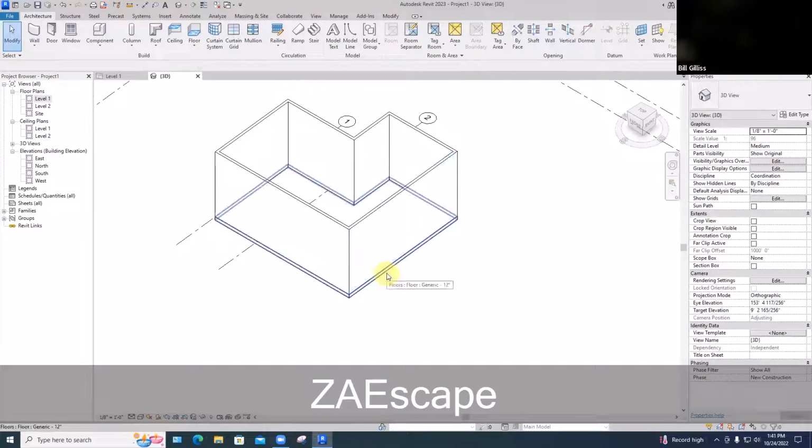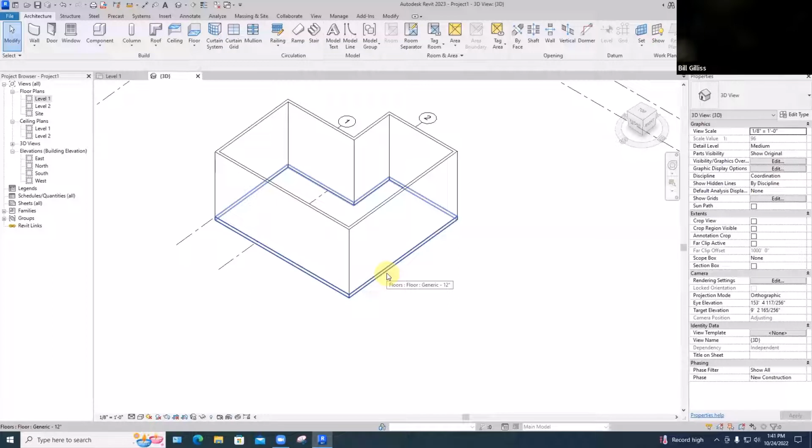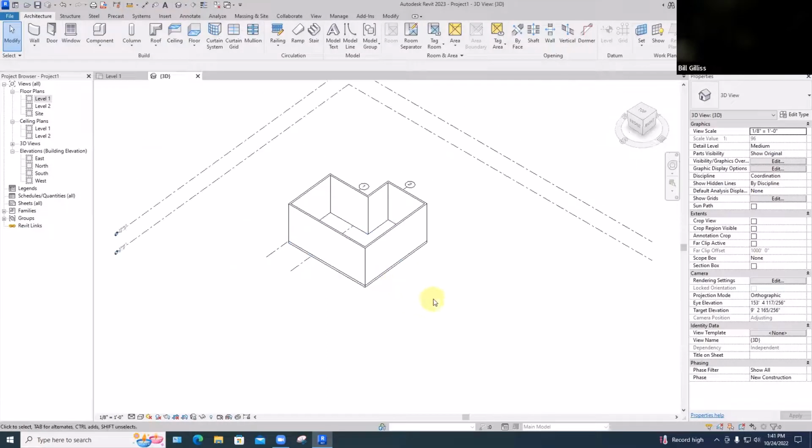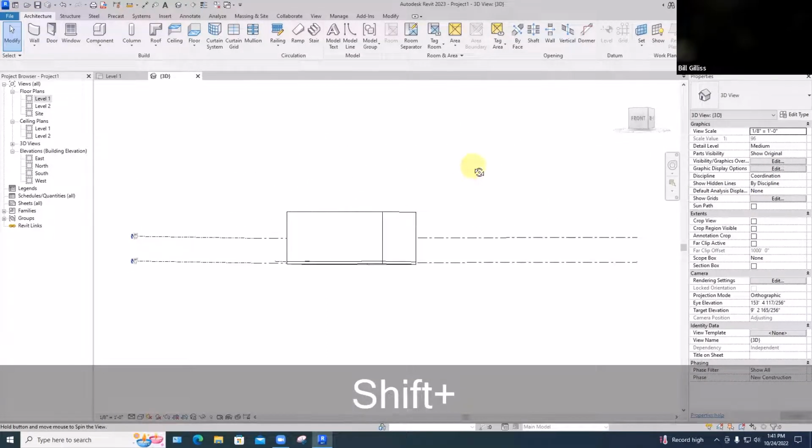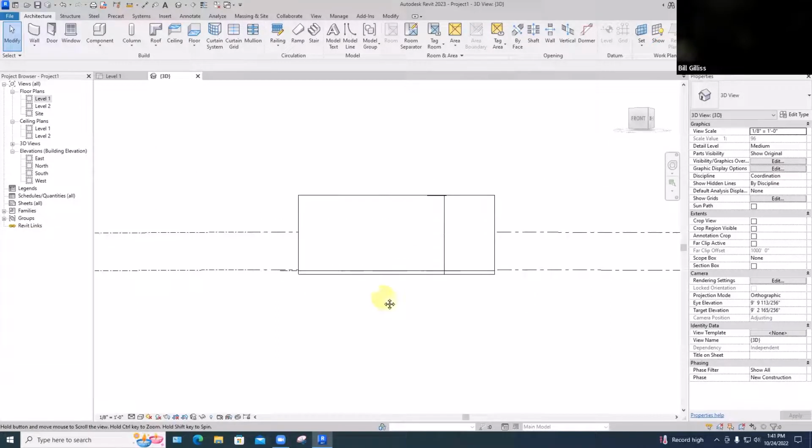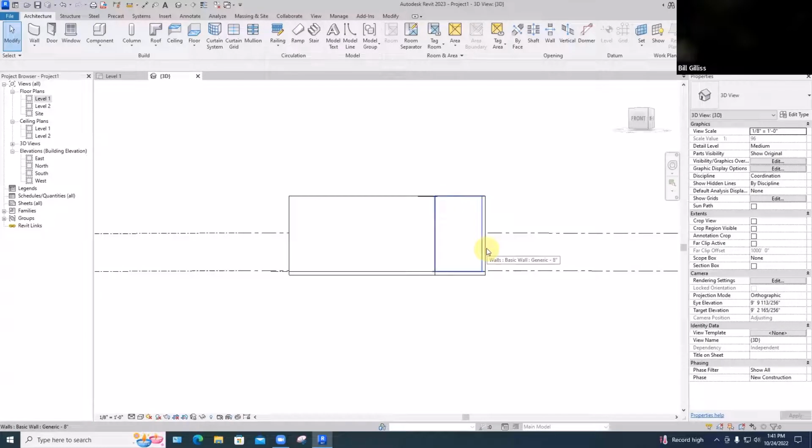And actually the floors don't go out like that, until the walls come down past it, which they don't, because right now the walls start at level 1 and the floor goes down from level 1. But you can see that what's happening there is that level, our level 1 here, is telling the walls where to go, where to start going up, and the floors to start going down.